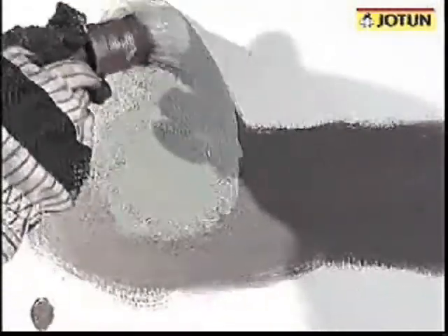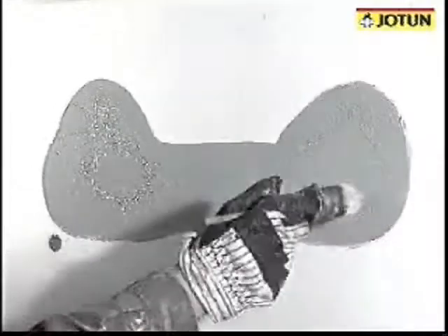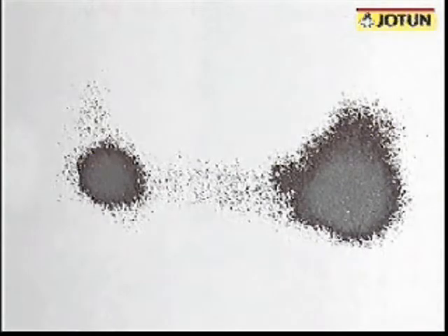In this case, solvents from the newly applied paint will cause the damaged edges to curl up. Even after 2 maintenance coats, the rough paint is visible. Damaged paint after spot blasting is a very poor substrate for paints, and corrosion will develop in short time.